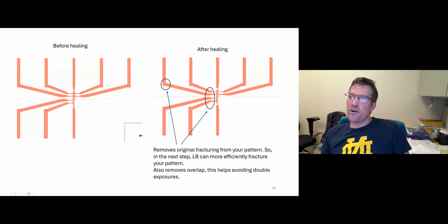Now, if you are here on your large part of your sample that is just kind of like an electrical lead of your devices, and you will have a larger area, then it's probably not a critical part of your sample, so you can be fine with that. But consider that here in the center, the lines are around 50 nanometers. And if this horizontal line is actually overlapping with the vertical line, then here in the center, you will have a double exposure.